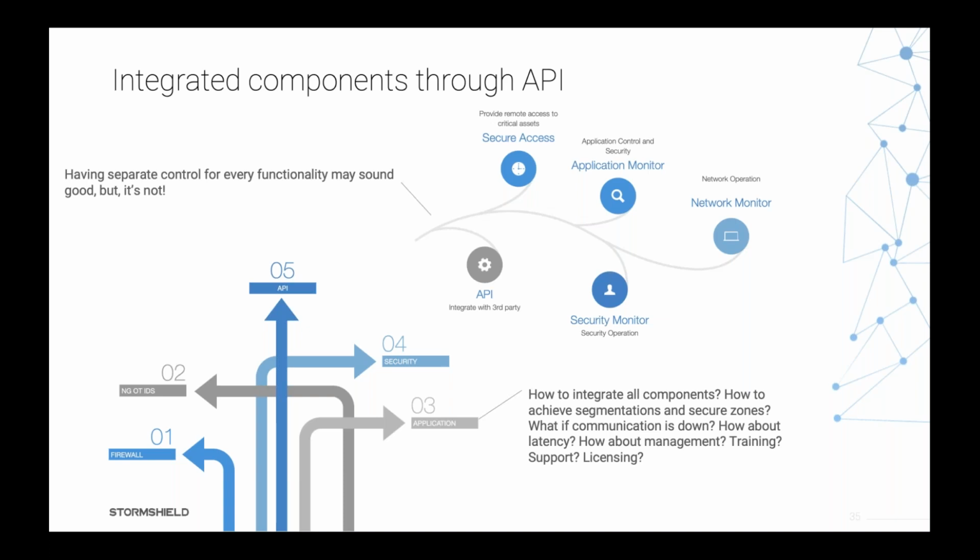But the problem is, you can see these different components, a lot of things are there. Sometimes you need an OT IDS integrated in the network, and you need a firewall integrated in the network, so they can communicate, because most firewalls cannot detect all types of industrial protocols, especially the protocols at the lower levels, I mean the Ethernet protocols, not the IP protocols, such as Profinet or IEC 61850, GOOSE and MMS. It's not easy to create simple signatures for these protocols.